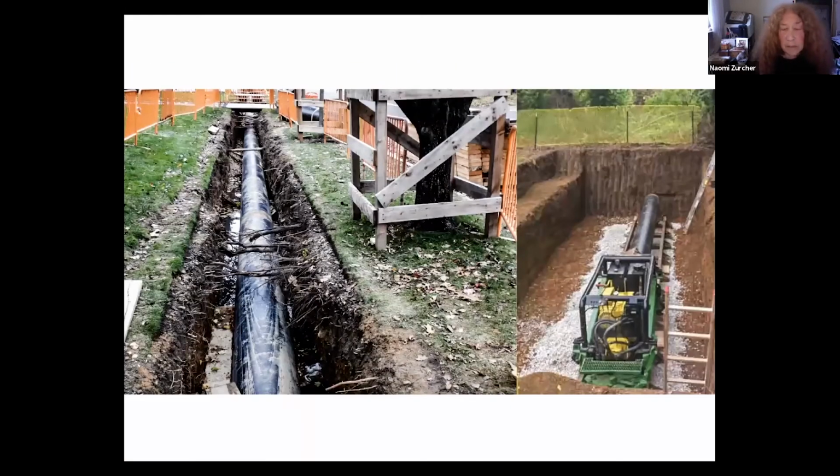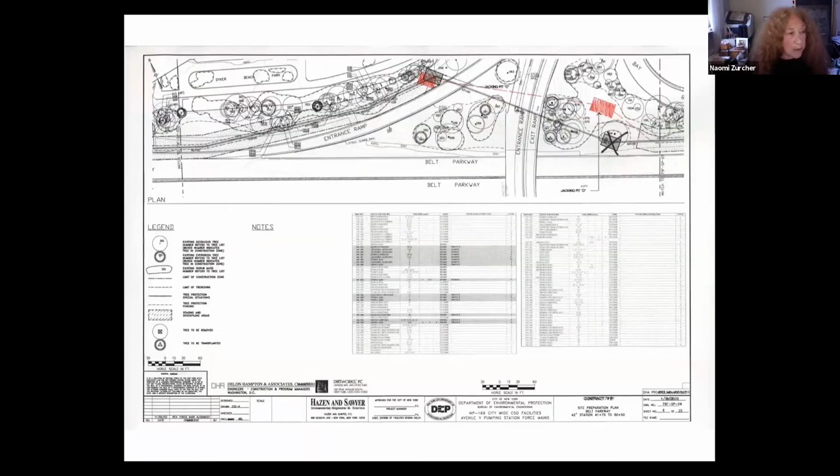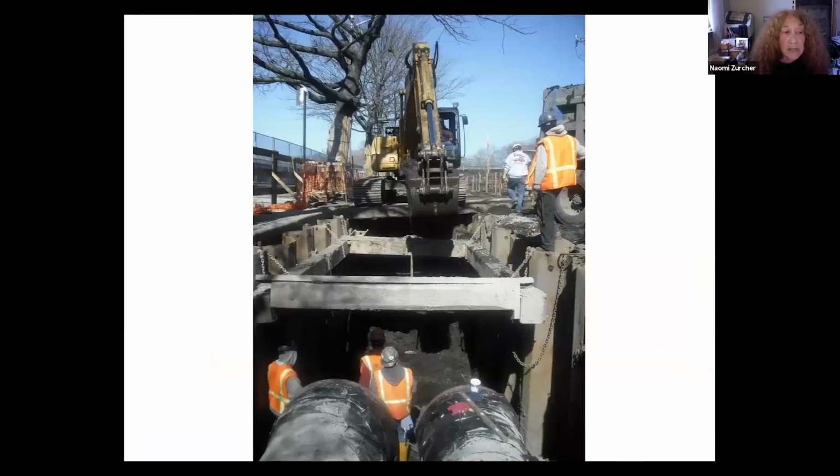To install pipes, conduits, cables, and the like, tree and landscape friendly design must consider the use of trenchless technology, normally only used to preserve hardscape features, to tunnel under roots. These strategies include microtunneling or jacking with send-receive pits, which must be well-sited and capable of receiving and sending so as to reduce impacts. The dimensions of the excavation will determine the need to sheet and shore to increase structural integrity.